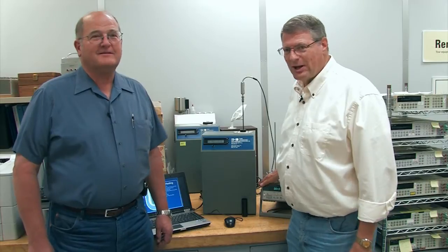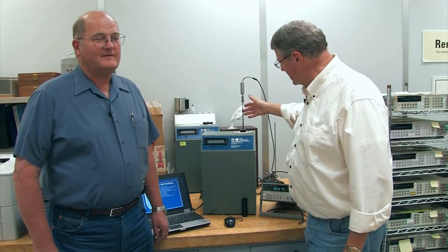Okay, so we've gone through quite a few things today. We've talked about what the heck the triple point of water is, right? Stan's explained that to us. He's explained how to realize a triple point using the techniques built into his product. Correct. And finally, we've shown how to use that to calibrate a system consisting of an SPRT and a measurement device to be able to accurately measure. Correct. And the uncertainty of the triple point of water in this situation is approximately a half millikelvin, and the ratio between that uncertainty and the uncertainty of the instrument and SPRT combination is about 10-to-1.